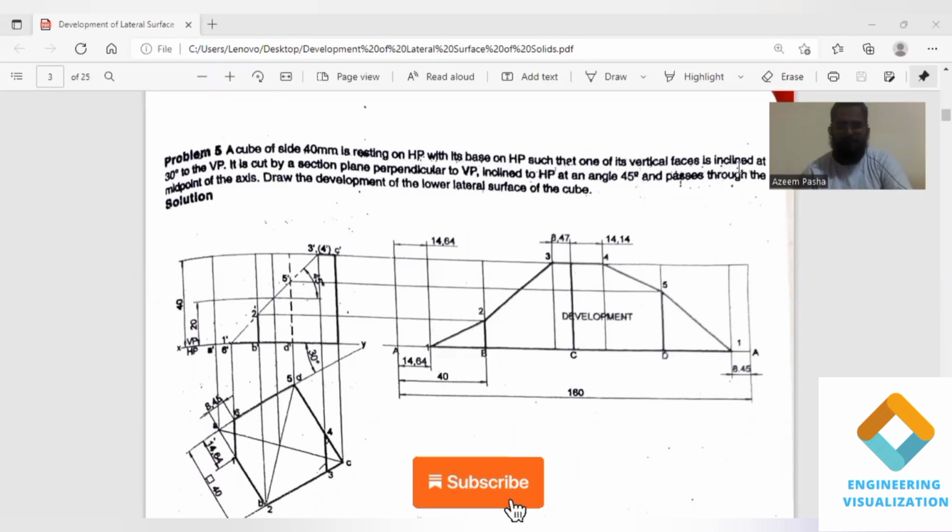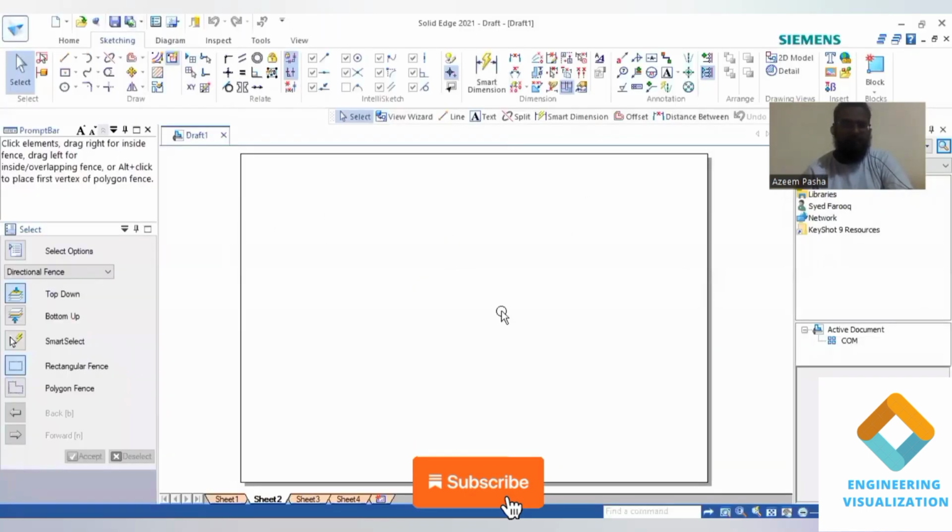You can see in this problem there is a cube given, of dimension 40, resting on HP with its base on HP such that one of its vertical faces is inclined at 30 degrees to VP. That means we have to draw 30 degrees. Then we have to place the square of dimension 40 on it. It is cut by a section plane perpendicular to VP and inclined to HP at an angle of 45 degrees, passing exactly through the midpoint. You can see the length is 40, so you have to take 20. At the midpoint you have to draw the 45-degree section plane, and we need to draw the development of the lower lateral surface of the cube.